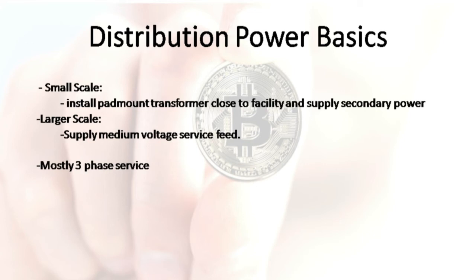However, with your mining operation, you will most likely be accustomed to the 3-phase 4-wire system, where it is usually supplied from a Y secondary, and it is essentially 3 wires of 3 different phases and a neutral. Less common will be having the 3-phase service supplied by a delta secondary transformer, where now you will have 3 wires instead of 4 going into your facility. The reason for only 3 wires is that delta connections do not have a neutral.